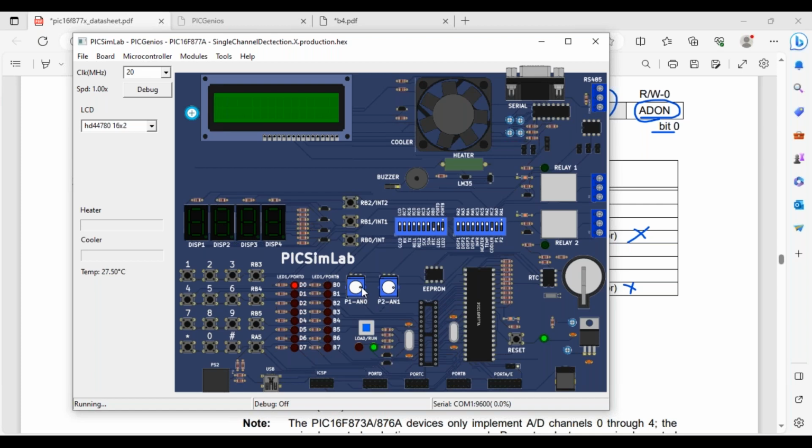Okay, I move to the left, the voltage is decreasing and the corresponding digital value is also decreasing. If it decreases lesser than 512, the LED is turned off. Actually, if I reach the lower end, it should not allow me to move after that, but in this case, I can move from 0 volts to 5 volts directly like this.